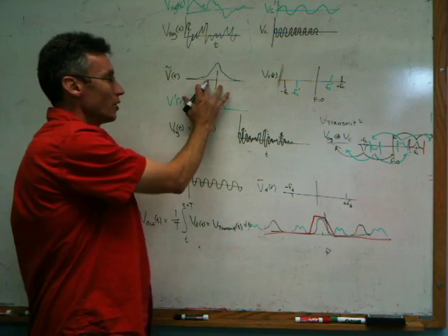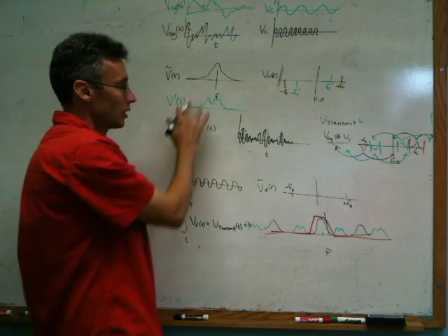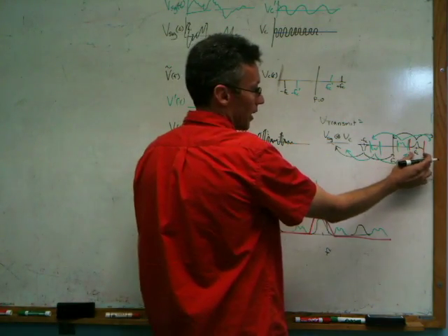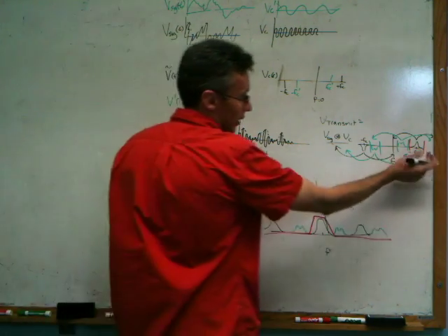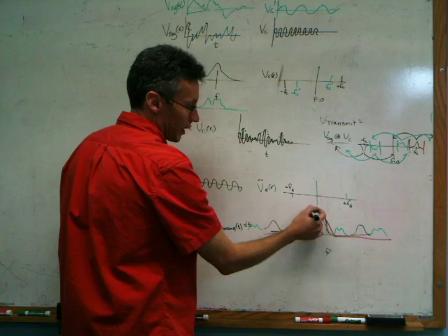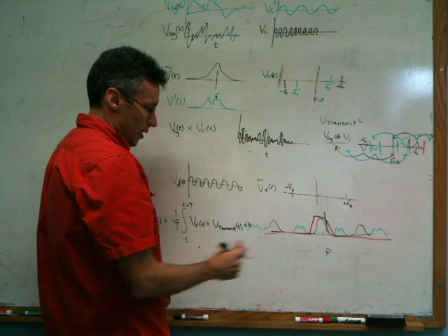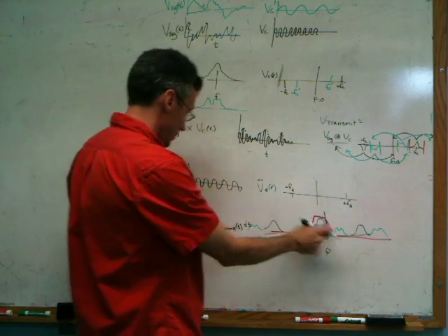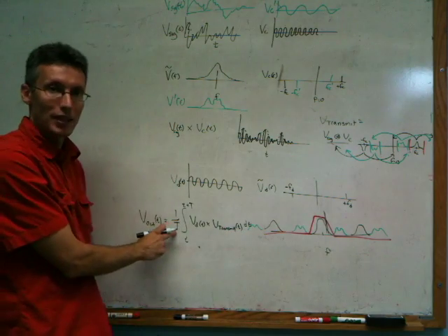If this is an audio waveform that has spectral content up to 20 kilohertz, then we might want 20 kilohertz wide channels, actually 40 kilohertz, 20 on each side, and then we want our low-pass filter to be at plus and minus 20 kilohertz. Knowing the frequency of the low-pass filter, that corresponds to the integration time.